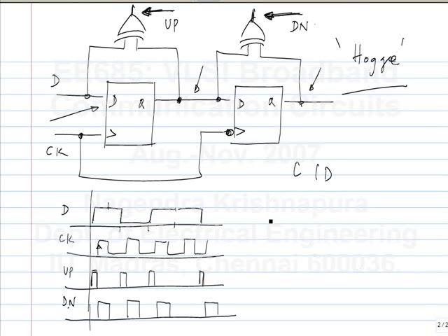What I mean to say is, let's say we have a long period without any transitions. And let's say these are the bit intervals. Now, after this transition, the voltage on the VCO control input is such that the frequency is maybe slightly higher than the actual frequency of the data. That is definitely possible, right? Because, as we discussed just now, the output of the charge pump is not identically zero. It is the response to the up and down pulses. So the VCO control voltage will have the correct average value, but it will have some ripple about it.